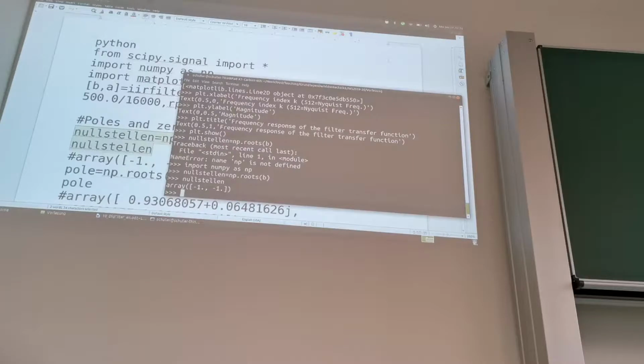And this comes from our substitution, right? We had this e to the j 2 pi divided by N times k. This 2 pi divided by capital N times k is our angle, which is at the same time our normalized frequency. So basically, making this substitution, z equals e to the j omega, means that in the complex plane, this angle is identical to our normalized frequency, where pi is Nyquist. Make sense?